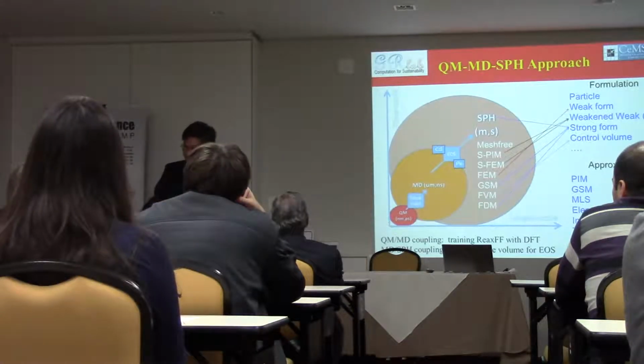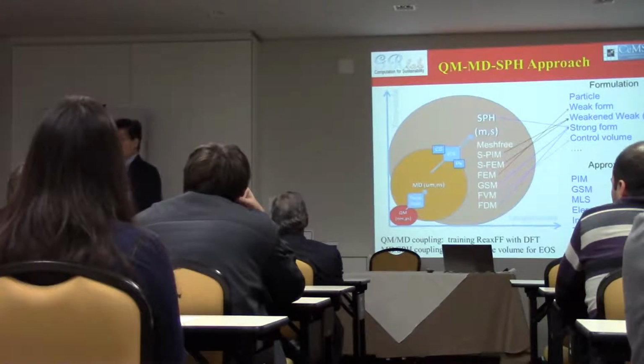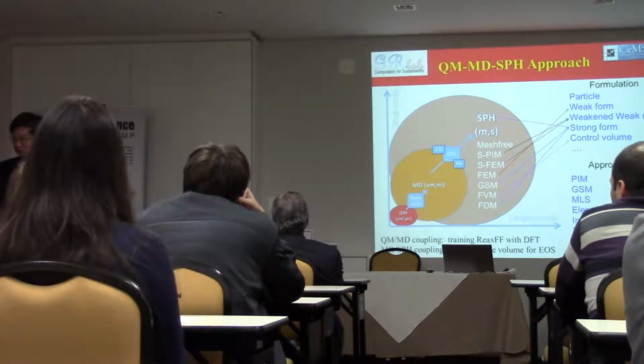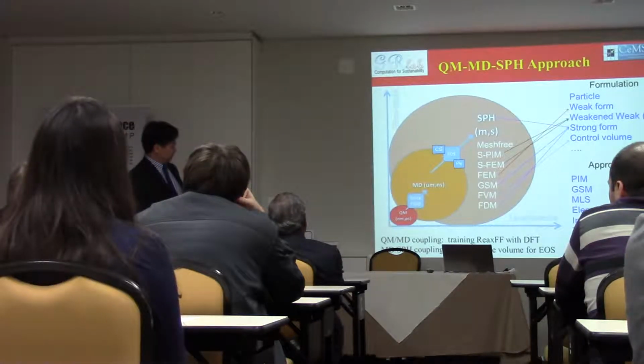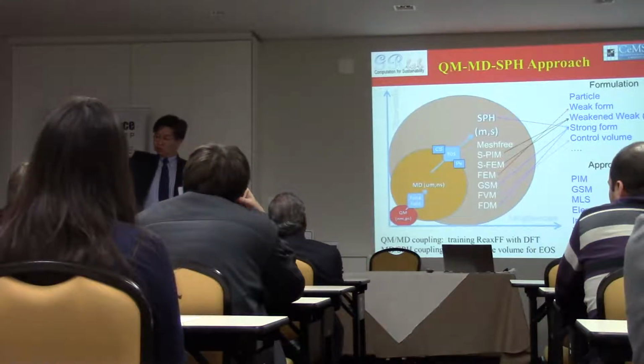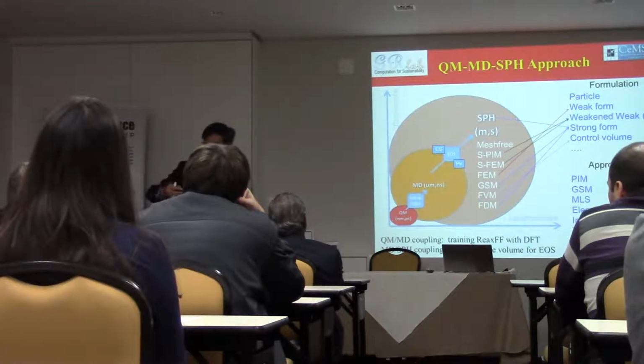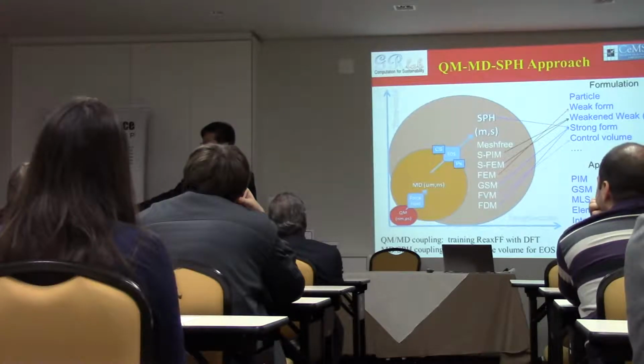But fluid problems are governed by the Navier-Stokes equations, which are not symmetric in terms of spatial differentiation. So even though you bring in the weak form formulation, the system equation that you create is still going to be asymmetric. And we know that if we have to solve an asymmetric system, it's going to be much, much more expensive.